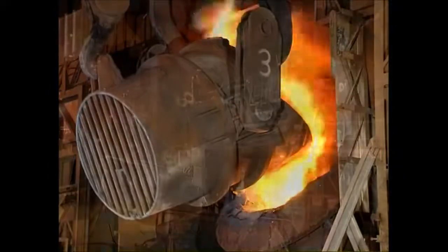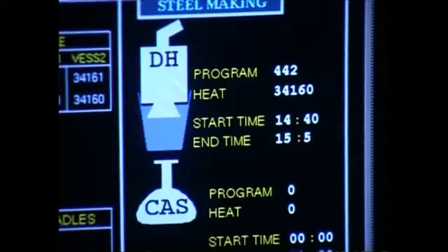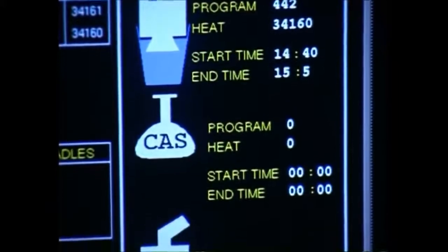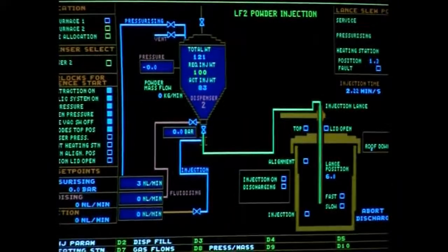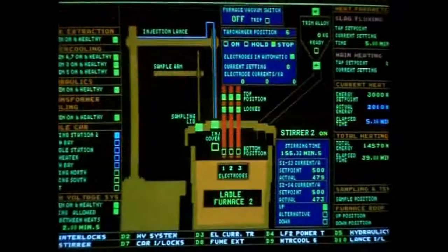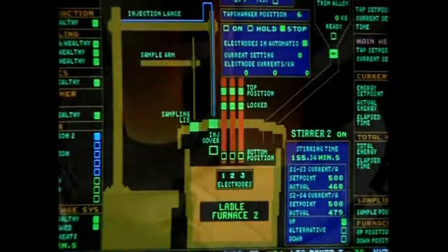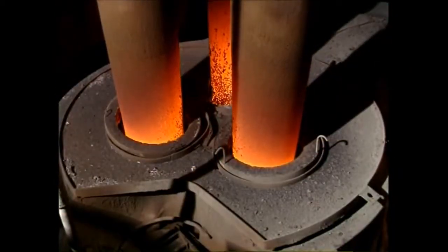After the BOS or EAF steelmaking processes, a combination of secondary steelmaking processes is used to further refine the steel. These specialist processes are designed to improve the consistency of temperature and composition within the steel. They allow the removal of gases such as hydrogen and the reduction of elements like sulfur and the addition of alloys and slags. All of this ensures the steel meets exact customer specifications before casting.